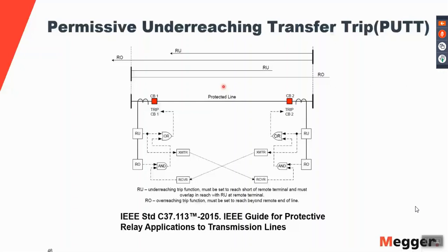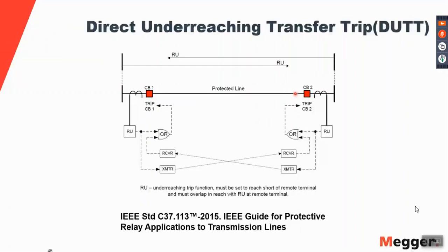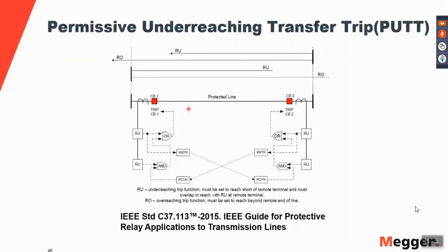There was nobody supervising this relay. It was tripping simply on the direct trip here. This relay was tripping simply because it received the trip command from this relay. In this case, it receives the enable, but it also needs the permission from its own functions.